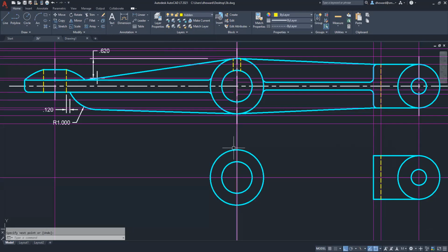And these two circles represent the completed pivot. So again, how are these two features connected? With a web across the middle and then these ribs on the upper and lower portion. Let's do the rib. The ribbing is really simple. That's just a basic tangent. Just go to my object layer and click on this corner and go to tangent up here. And you want to see that tangent symbol light up. There it is, and it will say the word tangent. Bam.